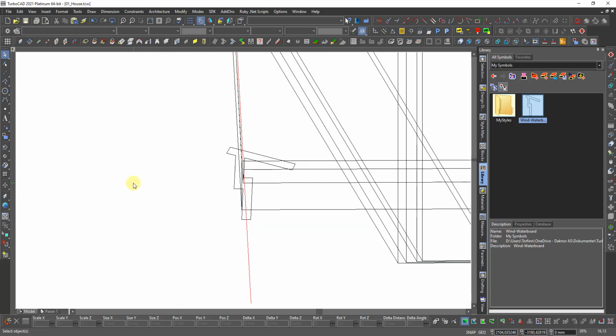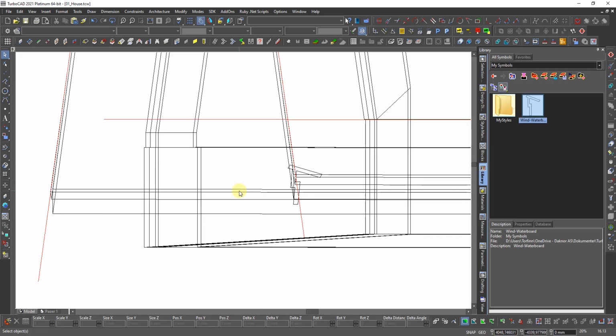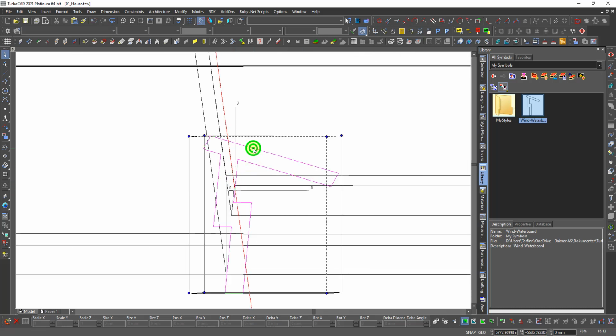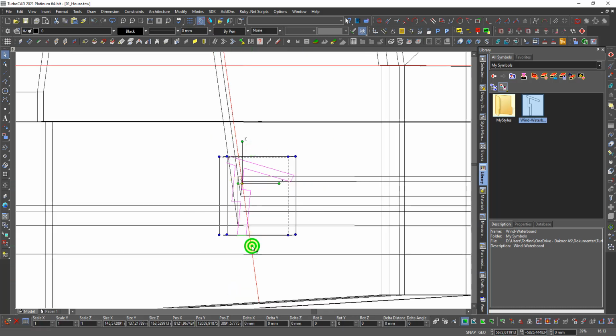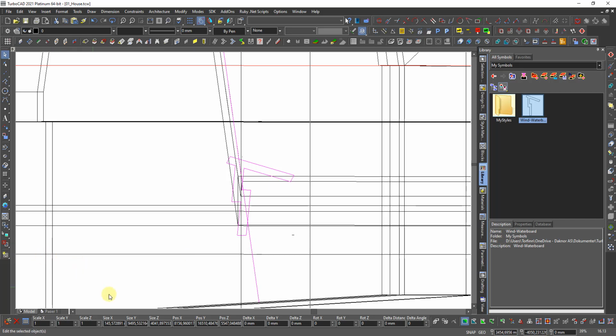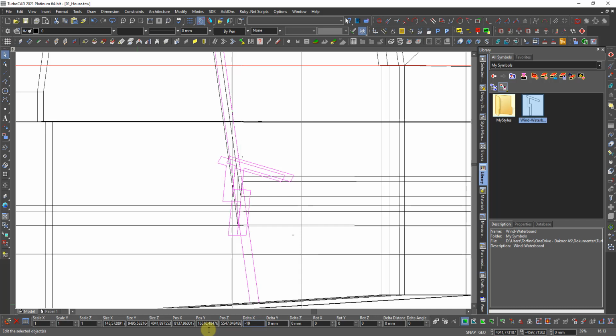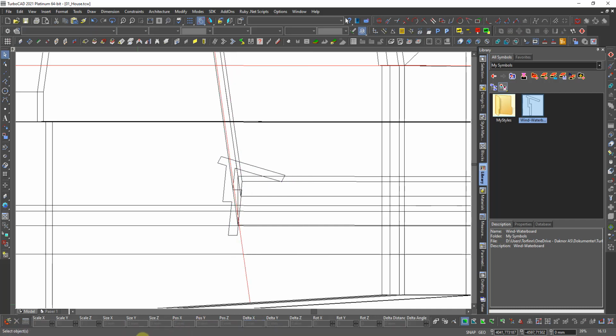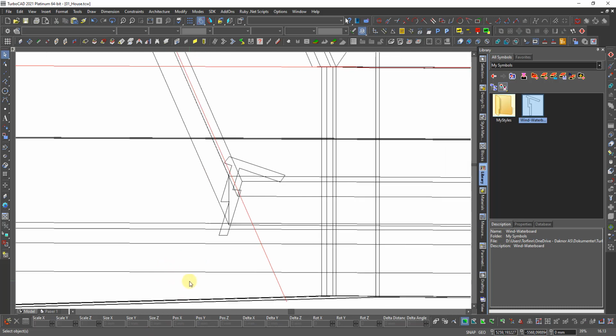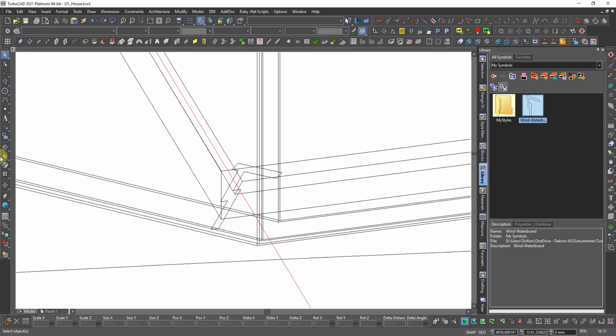If we move, that was 19 millimeter. I say this and this should be moved out 19 millimeter. That is minus X minus 19. Then it will be correct. And then we should sweep. A sweep tool is in here someplace, not in this, not in this, where does it hide them? Then I just sit in here, just extrude, and I should have sweep.